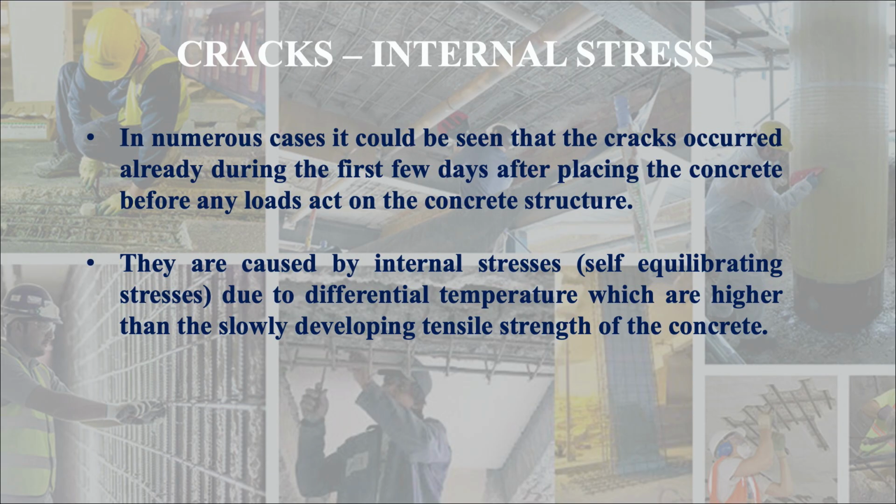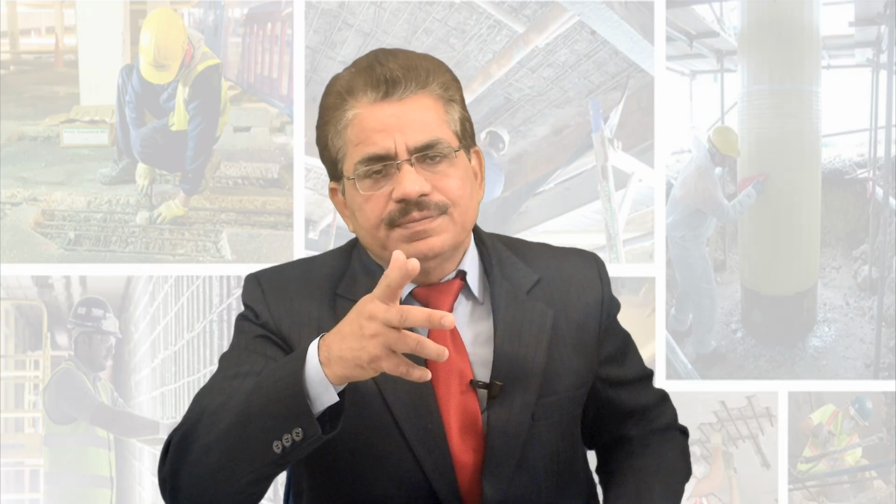Means what are these stresses? Caused by the self-equilibrating stresses due to differential temperature which are higher than the slowly developing tensile strength of concrete. So these internal stresses also cause cracks.